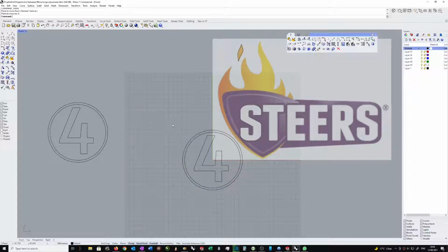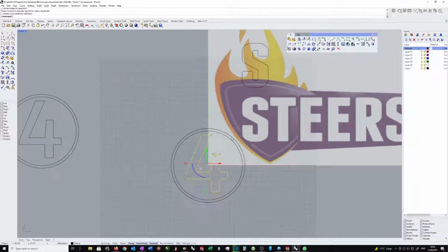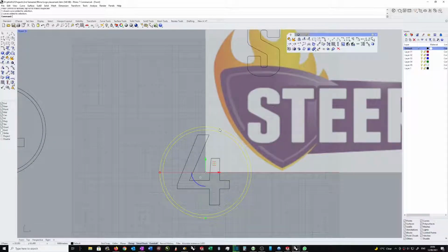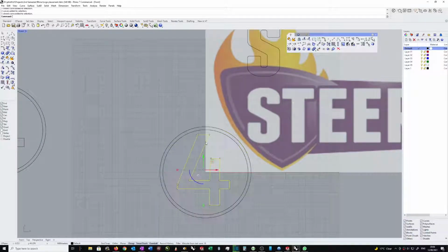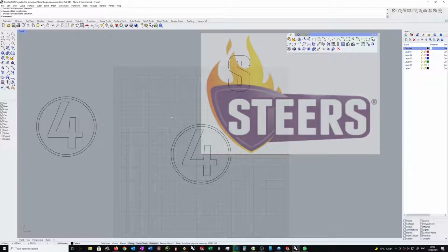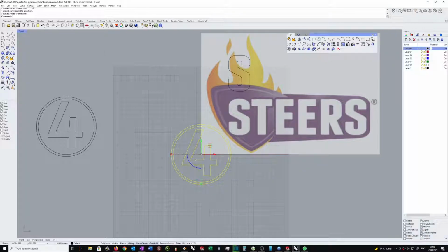And I'm going to use this logo to show you two other conditions that you need to watch out for. One is that you cannot put one sketch inside, or one sort of set of sketches inside another one, because that's one region there between those two lines, and this is another region here. And if you put the two together, SolidWorks won't be able to figure out which one to use. So I'm just going to export it in any case and show you how that works.